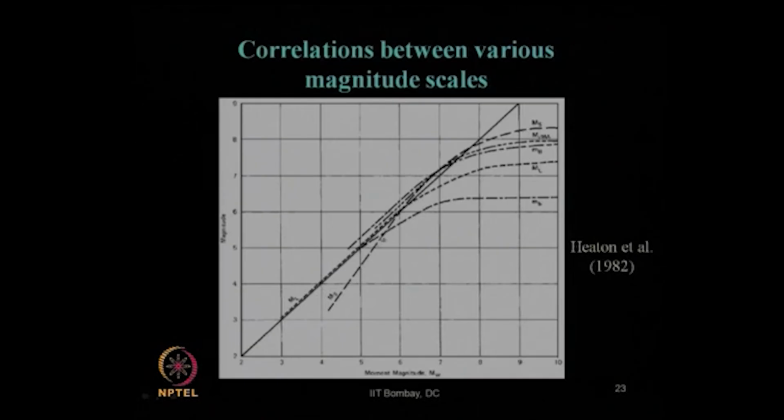You should use this curve, look at ML equals to 7. ML equals to 7 is here, this is the line 7, right, and that corresponds to an MW value of typically about 7.6 or so, a little beyond 7.5 as we can see. So, 7.6 or so. So, that is the way you can calculate or use the value of MW for your further engineering calculation.